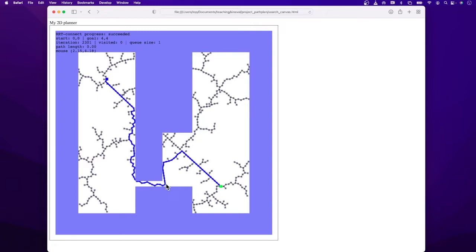But before then, because of the collisions with the world objects, the connection subroutine wasn't essentially taking place. And so that's what led to what appeared to be that more base RRT behavior during part of the run there. But you can see that at the end, we did find a valid path that does not collide with the environment from the starting configuration to the goal configuration. And so this then concludes our RRT Connect execution.